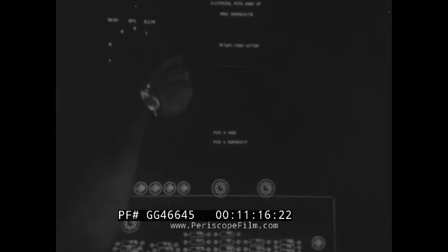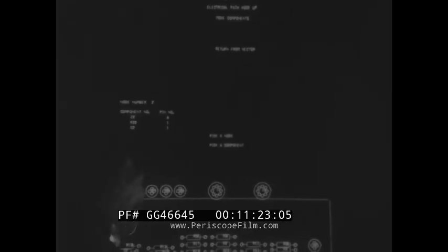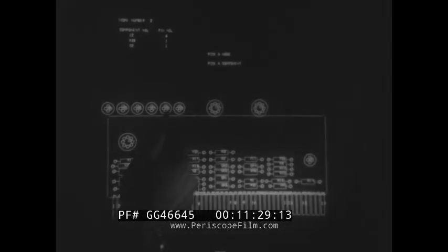Through the use of this internal numeric generator, the operator constructs node values. The computer responds by displaying a list of the node names and their respective leads of the node value. Through the selection of node 2, we can see that the components R23, C2, and Z2 were pre-placed near pin 2, which in this case has a node value of 2. By picking the component name R23, the computer responds with a group of new options. These options deal with the manipulation of the components selected.